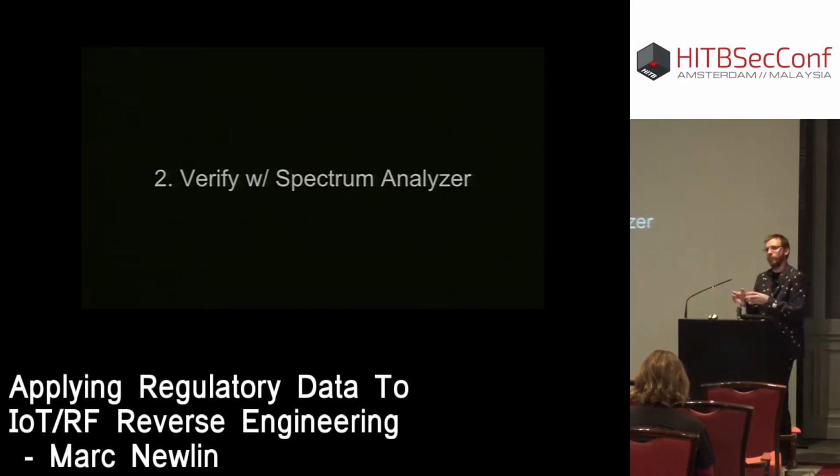So now that we have this information, we can have the device generate some traffic, in this case moving it around or clicking the mouse button or whatever, and look at that with a spectrum analyzer using a software-defined radio. And with this, we can confirm whether or not the information that we have so far is accurate.